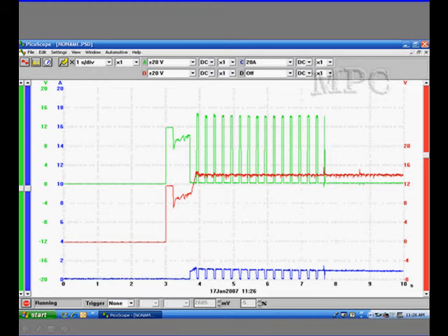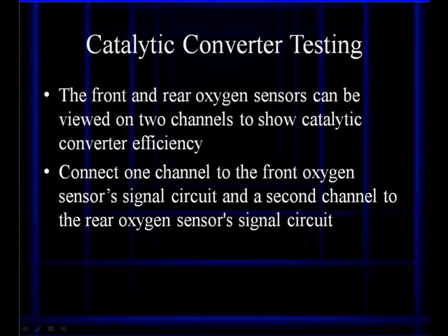So we can use this as an example of, hey, you can get a lot of stuff out of an oxygen sensor heater circuit. Now, GM and Ford don't have the control type that you see here, and basically you would use a low current probe and then, of course, test battery power to it.